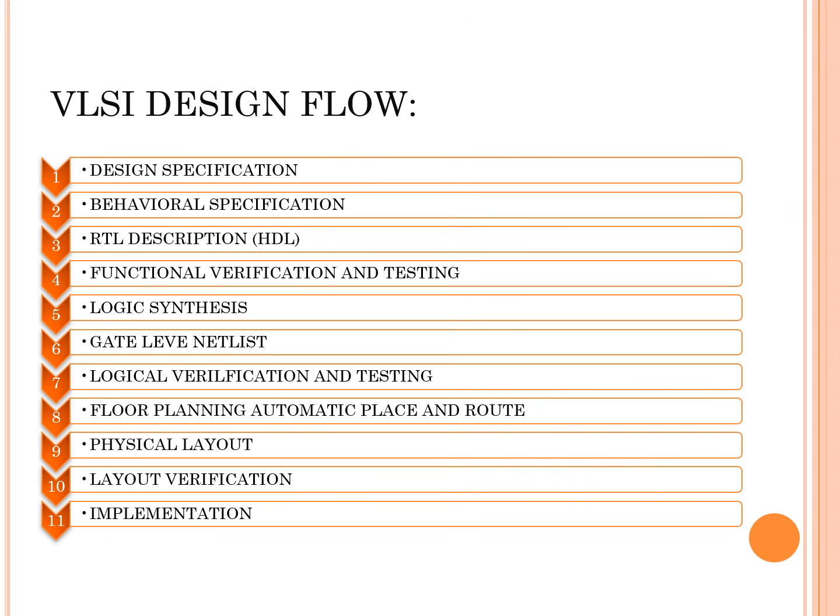Then comes the logic synthesis, where the RTL code is converted into a gate-level netlist using standard cells from the library. The gate-level netlist represents the entire design using logic gates and interconnections. It's like the blueprint of the hardware. Here we do another round of verification to check that the synthesized gate-level design still works correctly. No surprises at all. Now it's time for physical design.